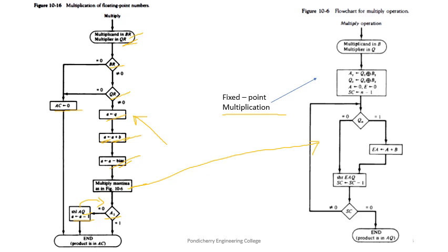The multiplier and multiplicand were both originally normalized fractions. So what is the smallest normalized operand we can have? It can only be 0.1 because it's normalized. It cannot be 0.0 something, it should be 0.1. If both are 0.1, the product's worst case is 0.01, so we can have only one 0 as the most significant digit.